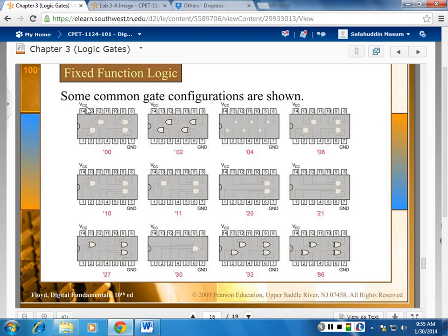Because there are 3 gates, right? Do you see it? Let's say 7427. There are 3 gates here, right? Which one are you going to use? Any one. It doesn't matter which you use. Don't assume that you have to use the first or second one. You can use any of those if you need 1. If you need 3, then you'll be using all of those. Now, let me show you something here.